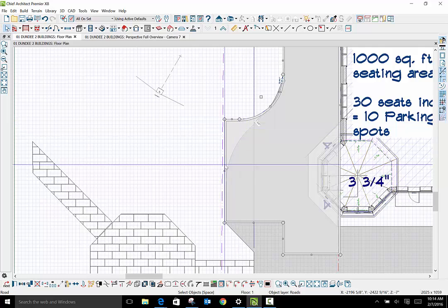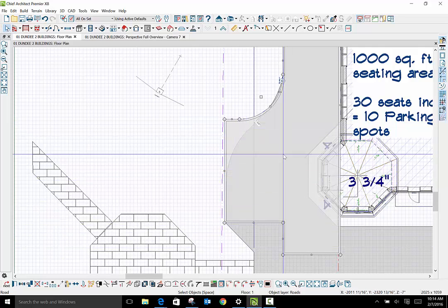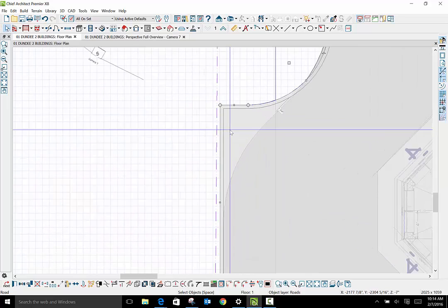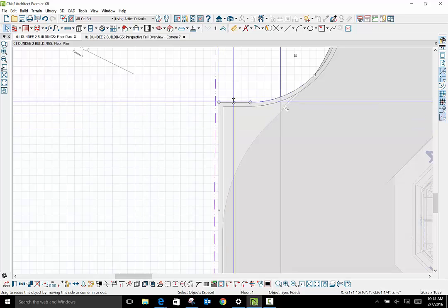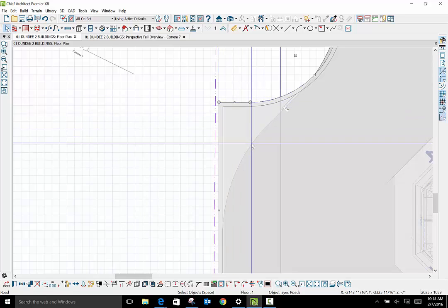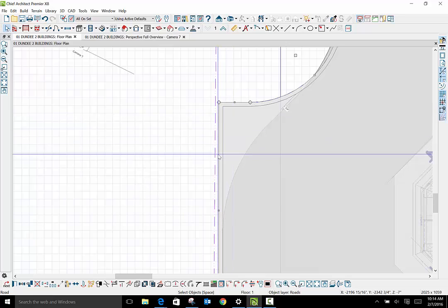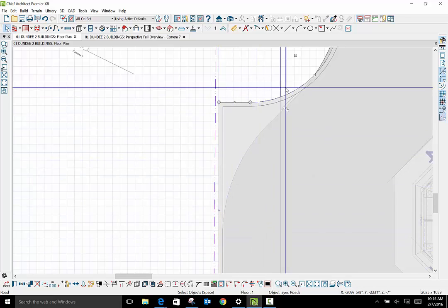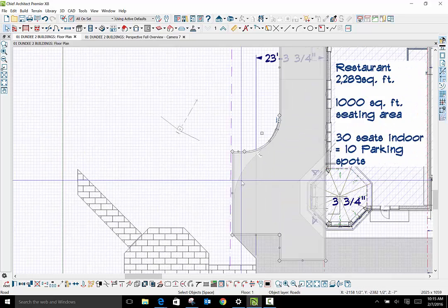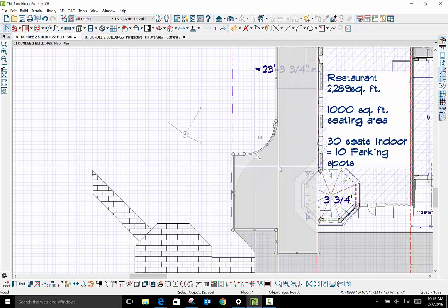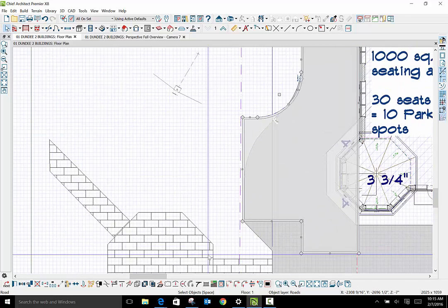Just keep that there and put a small radius there, which I think we will try to do, because we only got 1, 2, 3, 4 feet of segment here. So let's put a 6-foot radius, fillet it on here, and call it a day. Not get too crazy. We'll let this little engineer play with this one.